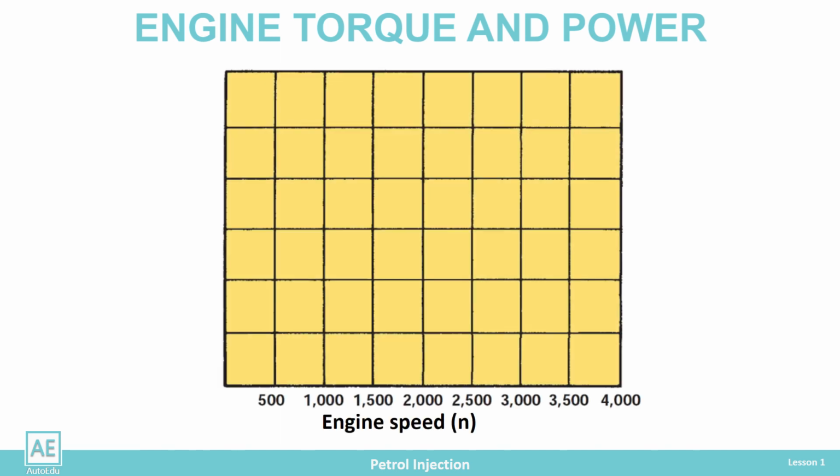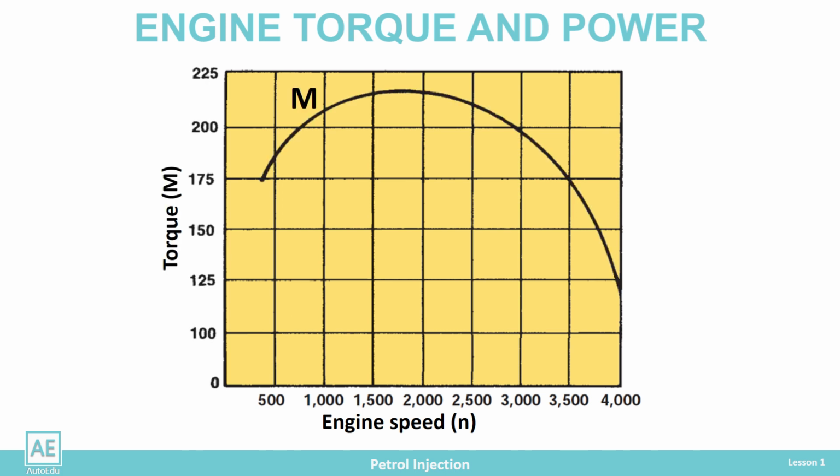In a naturally aspirated engine, the combustion chamber is only partially filled with the mixture due to the resistance of the air flowing through the intake manifold. The maximum engine torque occurs in the range of low to mean engine speed when the filling of the cylinder with the mixture is best. Then the engine is most efficient and has the lowest fuel consumption. As the engine speed increases further, the torque drops.